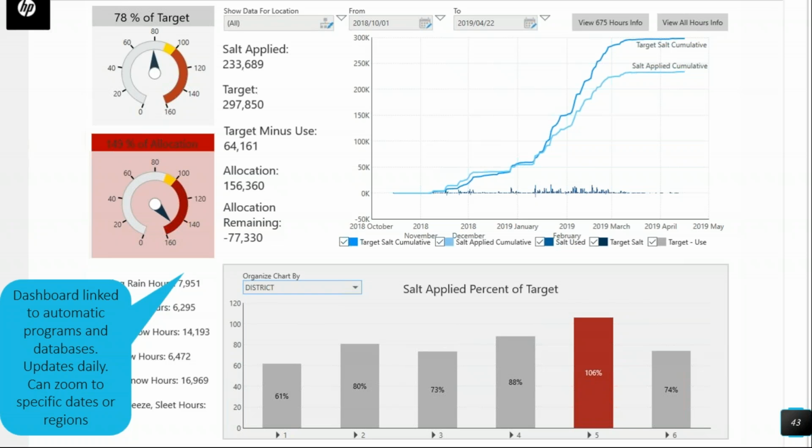So I would expect that there might be some times where your heated pavement cost is X, and you might have used a little bit of material cost Y on it, and you're probably still plowing it, and so you still have a little bit of labor cost. Your combined cost would be how you might compare it to the other places that maybe don't have a heated pavement system. You may spend a lot less on material, and a lot less on labor and equipment, but you spend something for a heated pavement just to run it, whereas the other locations would just have the labor, equipment, and materials.